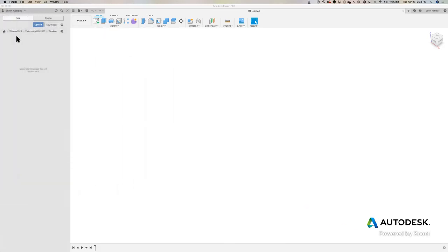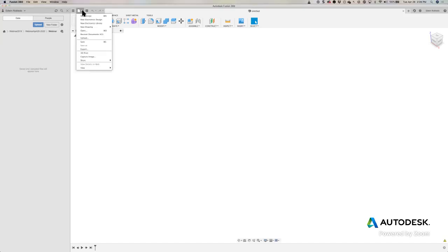So the correct process would be from Fusion 360. I open up, for those that are arriving a little late, I'm seeing the chat really growing a lot. What you're going to do is create a brand new electronic document. You're going to find that option under the pull down menu where it says File. You have two options here, electronic design or electronic library. We'll work with electronic library in a minute. Let's go ahead and just click here where it says new electronic design.